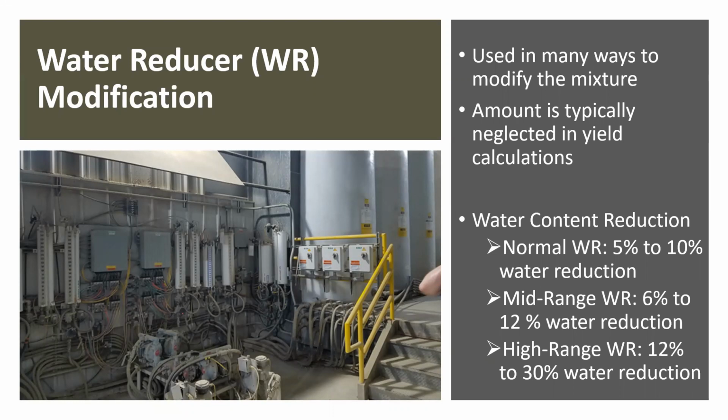So imagine, for the most part, when we talk about water reducers and air entrainers, the amount of weight that they contribute to our yield is maybe like a pound out of 4,000 pounds per yard. So they're like nothing. You don't even notice the decimal difference really. Now accelerators, if you're using 3% non-calcium accelerator, that's 3% of the volume. So you need to calculate the pounds.